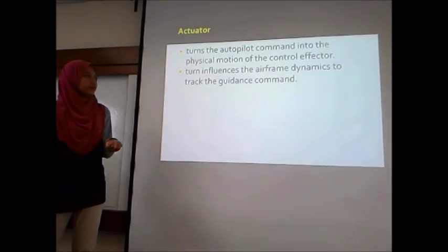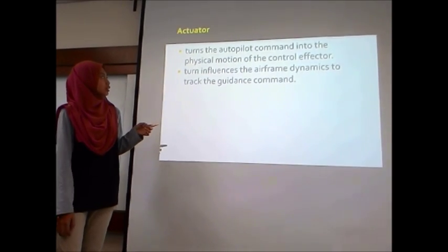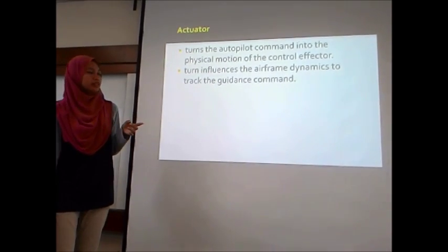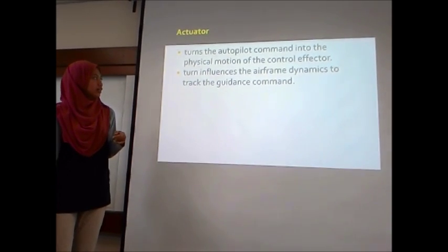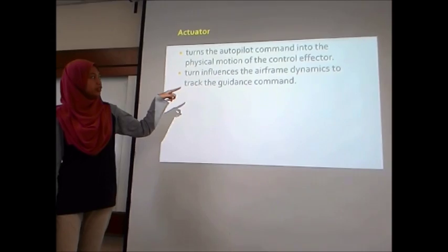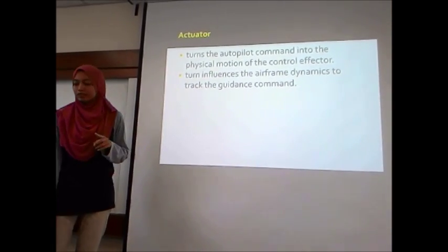So the first thing in the system is the actuator. The actuator turns the autopilot command into physical motion of control effect. This autopilot influences the airframe dynamics to track the guidance command.